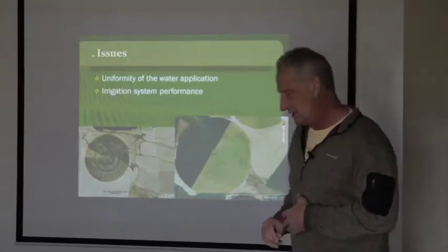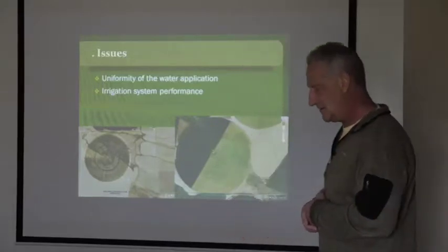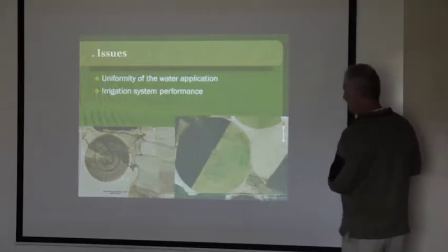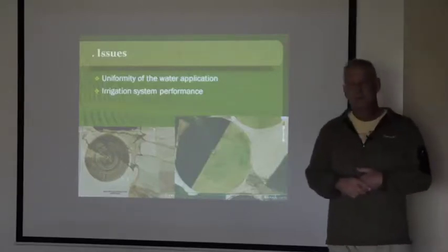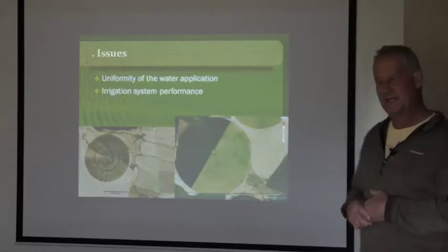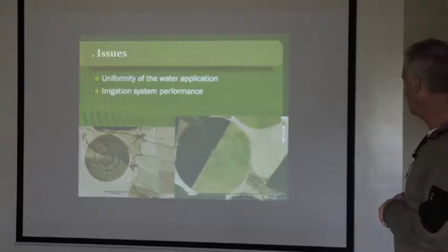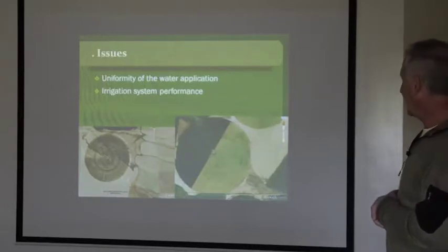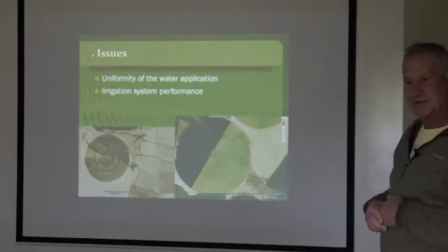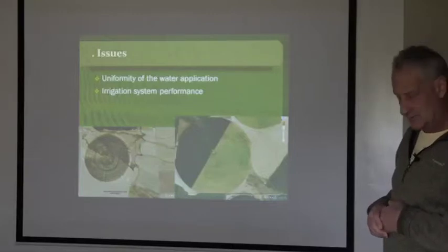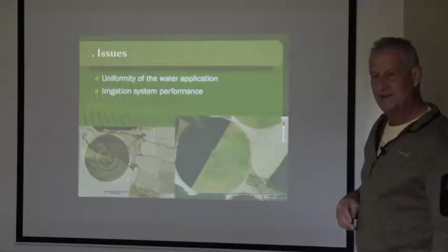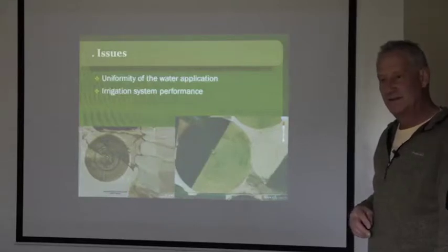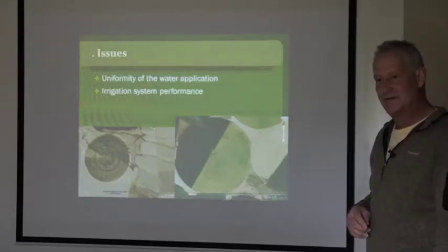So are there a couple of things that could be happening there on the one on the right? Like possibly plugged nozzles, but also your wind speed, and the speed of your mover. Would that cause that? Yeah, I mean, if you have it on at a tenth of an inch, and you're moving around there, and the wind's blowing pretty hard, you're going to miss a lot of crop.